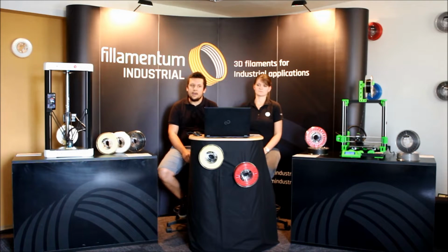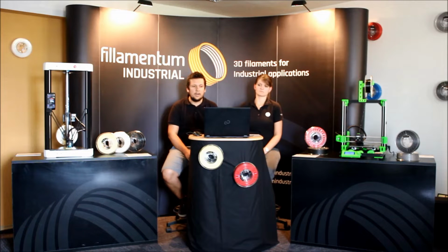And if you have small features or are printing several small parts, there is a requirement of about 4 times the nozzle size, because if the part is too small, the material doesn't have enough time to cool and results in failed prints or blobs. So 4 times nozzle size is something you should keep in mind in the design.